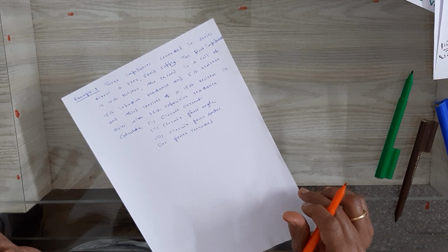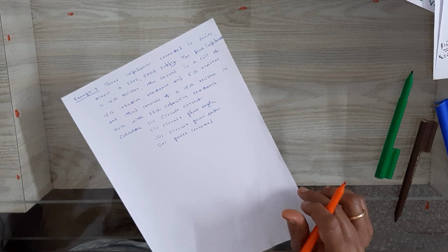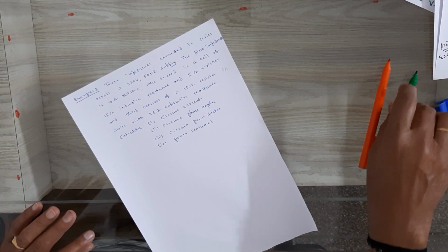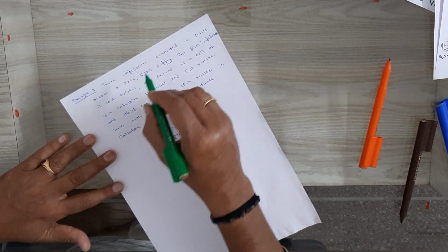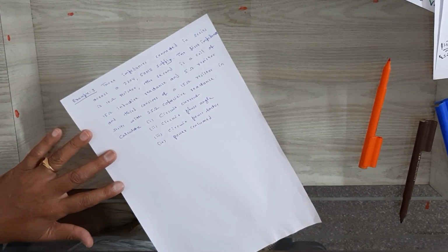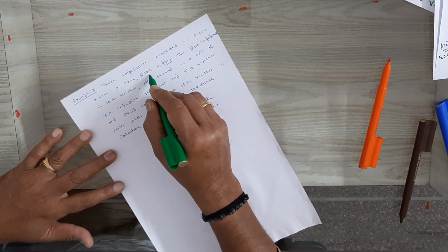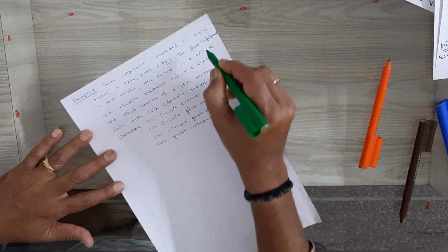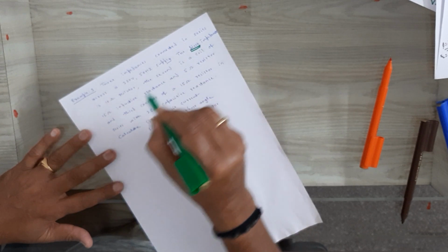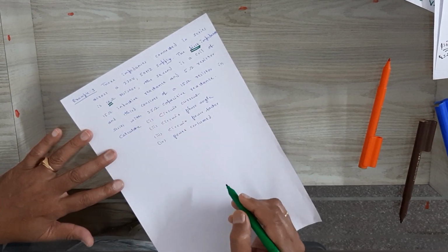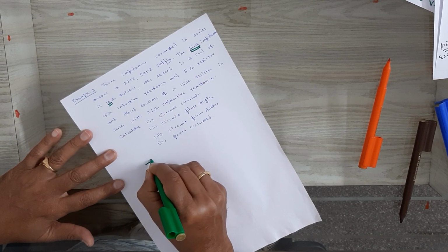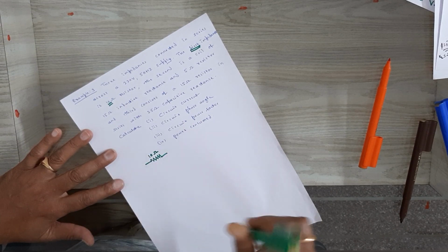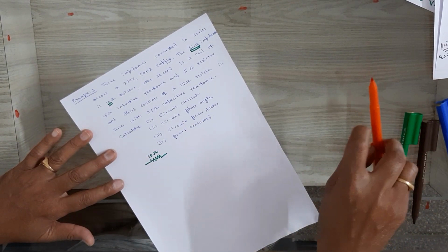There are 3 coils having a combination of either resistance and inductance or resistance and capacitance. You will draw the circuit by reading the statement carefully. 3 impedances connected in series across 220 volts, 50 Hz supply. The first impedance is only a resistance having the value 10 ohm. Therefore, I will draw a resistance having 10 ohm.